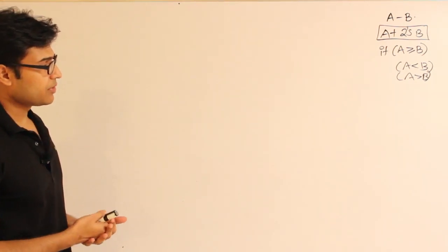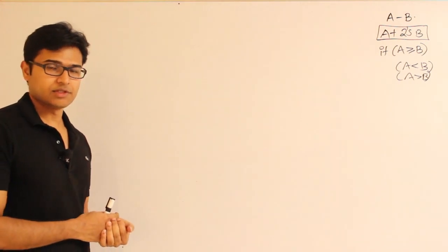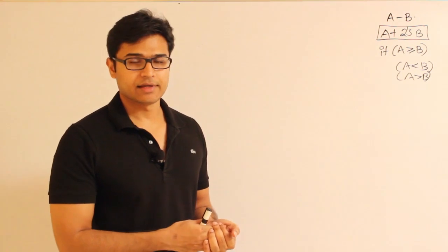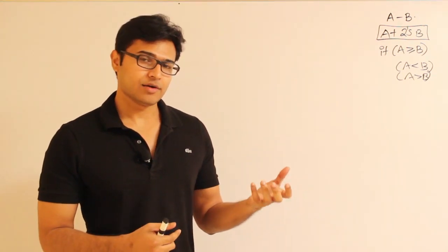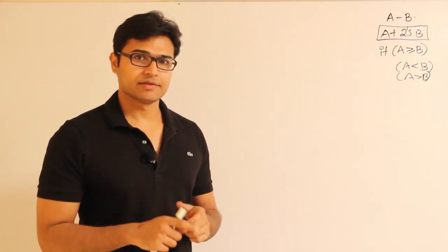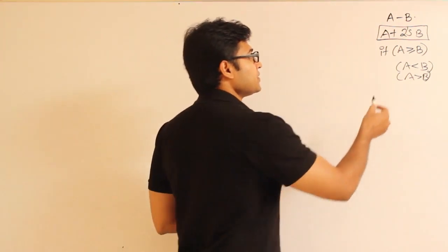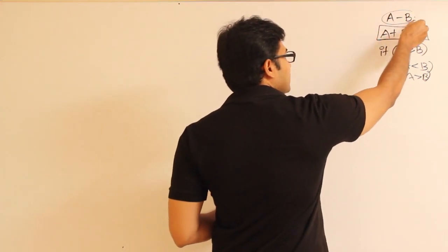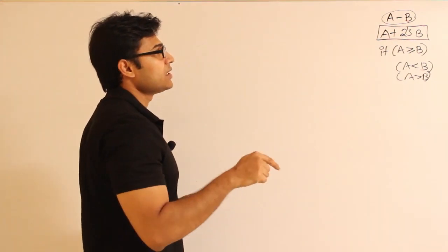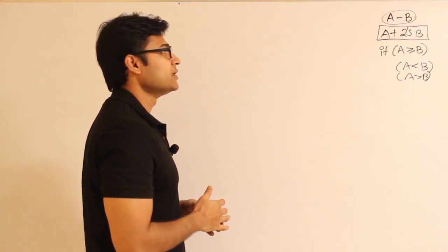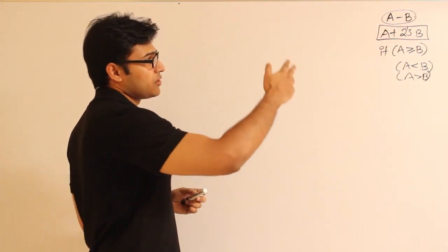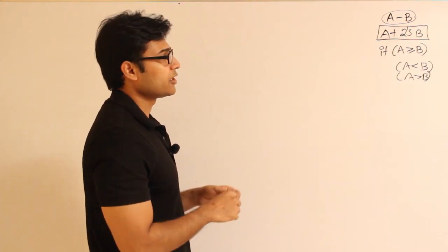One such set of operations is: branch if 0, branch if not 0, branch if greater, branch if less, like that. The underlying concept is that it will take two operands a and b and perform a minus b, and it will not save the result. The CPU will not save the result anywhere, but it will use the status flags to set some of the bits. Now using those status bits, we should derive which of these conditions is true. That is all about this topic.